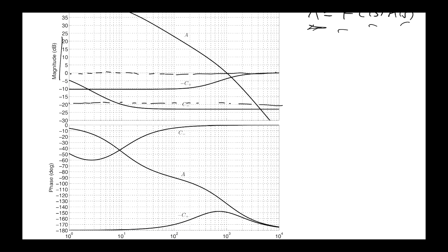And the thing to note in the solutions here is that just so that everything can be drawn on the same diagram, the lead compensator, which always gives you positive phase, all right, is drawn down here by multiplying it with -1. Right, just so that it can fit on the same thing. But this is really up here, all right?